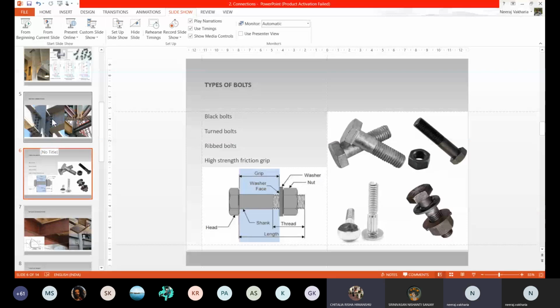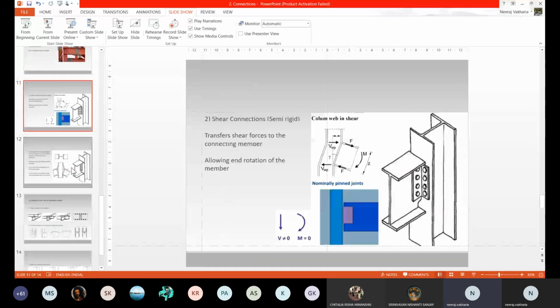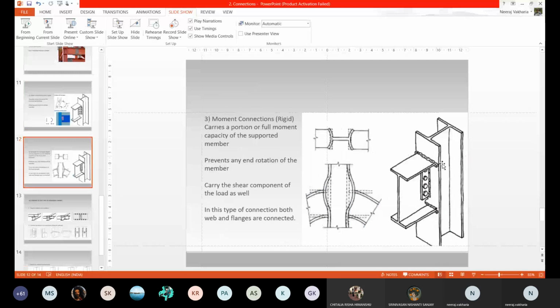If we weld it, then we don't require bolts. In this image, what they have done here is they have welded this plate, the cleat which you see, the rectangular cleat. It is welded to the I section or I column, but the welding is not done to connect the web to this column in this particular image.